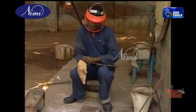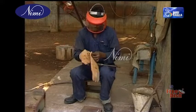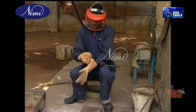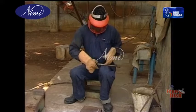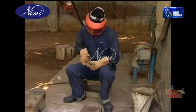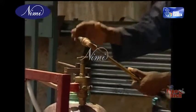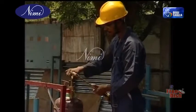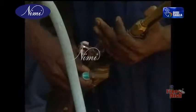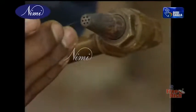The welder uses all personal protection equipment such as safety shield, gloves, safety shoes, etc. The workman chooses the appropriate size of nozzle for the cutting torch, and the cylinder valves are opened slowly using the key, and he tests the gas flow and also cleans the nozzle for free flow of gas.